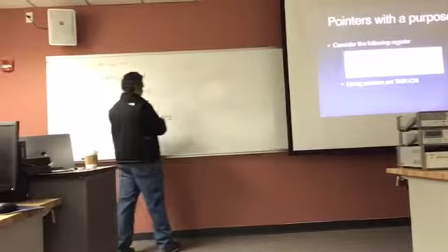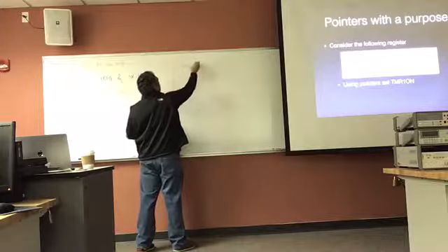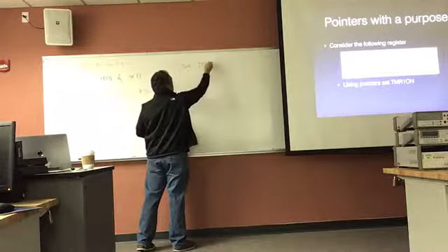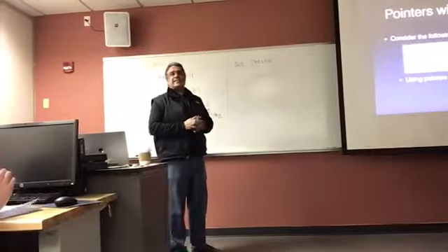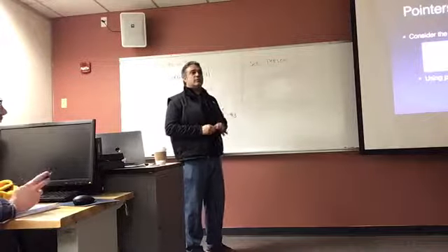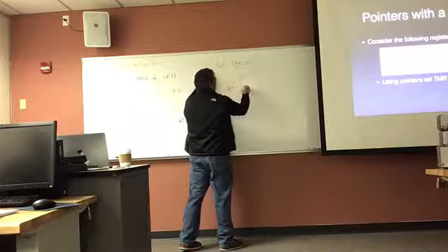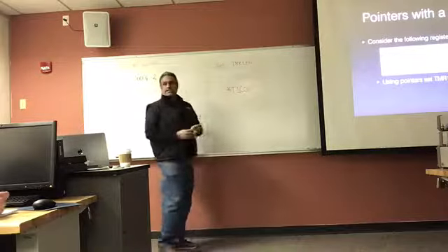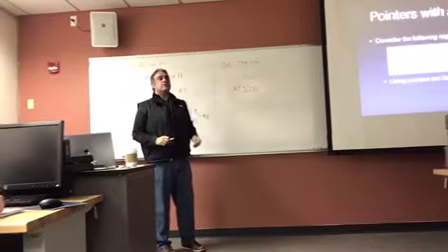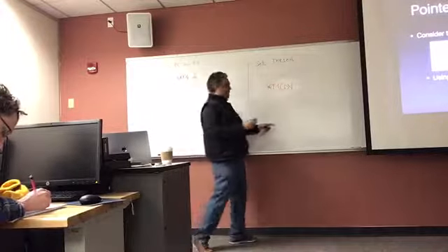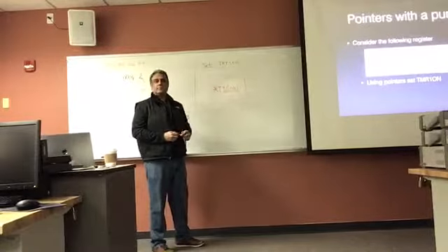Ready? I'll get it started. I'm going to set the circuit called TMR1 on. That's the name of that circuit, okay? That circuit is inside a register called T1CON. So I go, this is where, right? That's the circuit I want to mess with, right? What do you want to do? I want to set. So then I go, set, right?